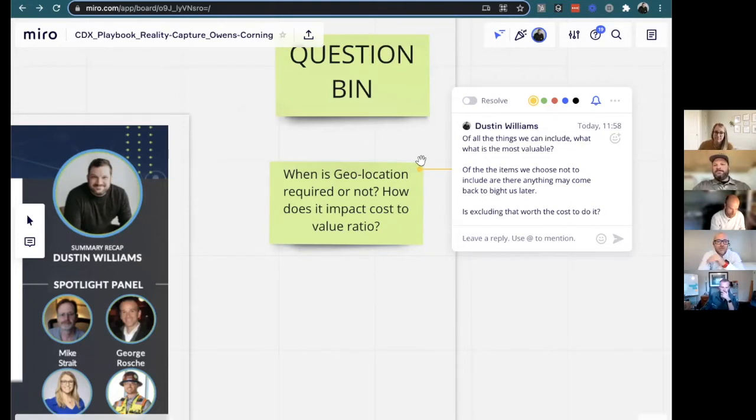And it really is a best practice. It should be looked at as a best practice to have some sort of survey control tied into your laser scans, because that's how you're going to align your data. Coordinates and alignment is a fairly complex thing that the industry at large has been trying to communicate to folks for a long time.